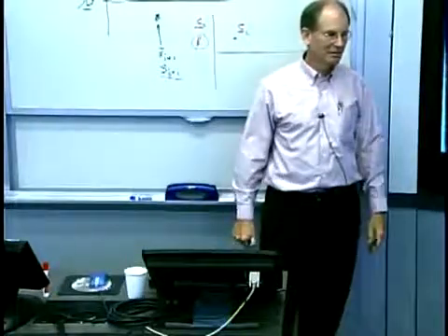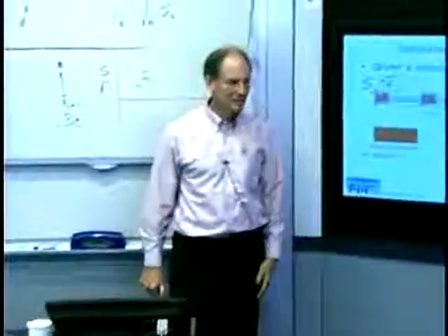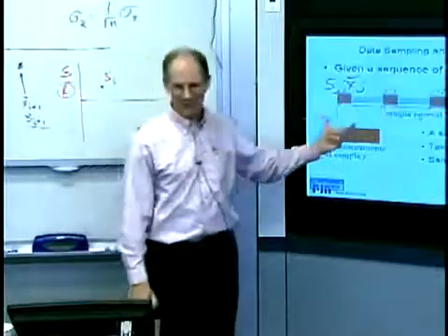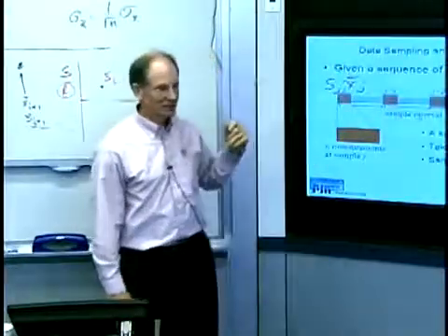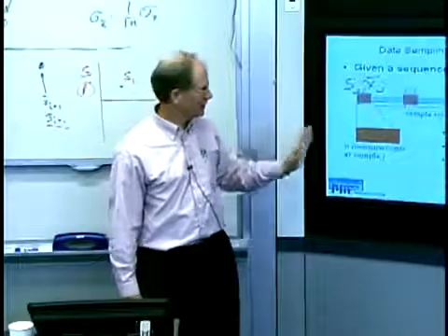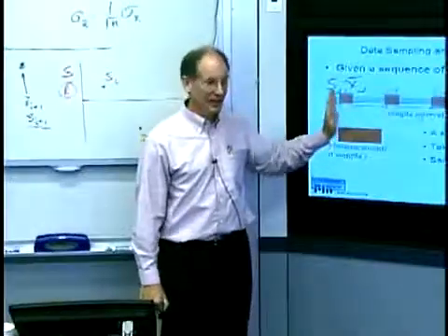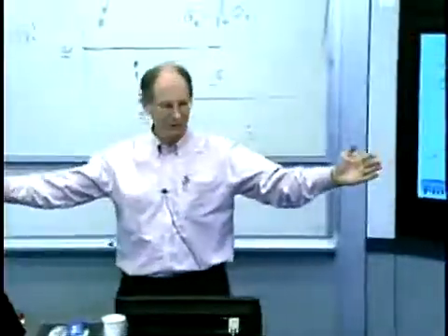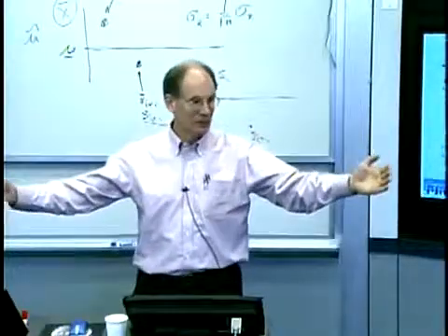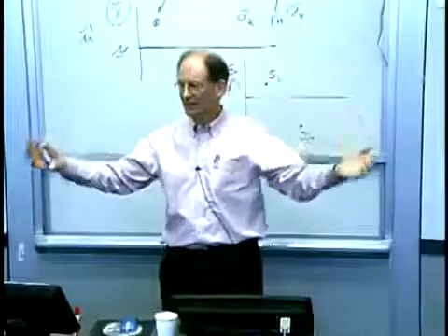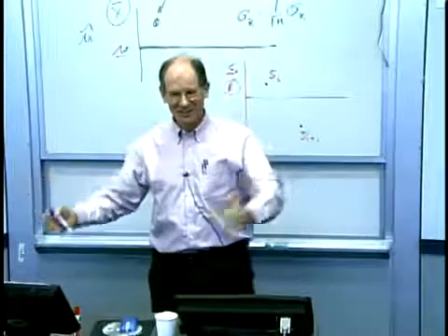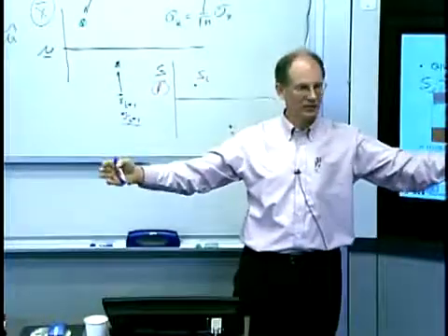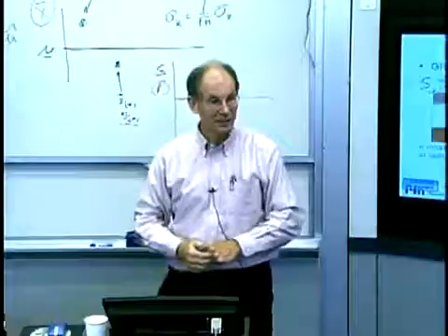Also, it would depend on your cycle time too. I mean, if your cycle time is 15 minutes, to get a sample of size 50 isn't really that hard. Yeah, it could take you all day to get a decent sample size, right? And there's a real issue here that comes up called time variability. If you took a large sample, 50, 100, a whole day's worth of production, and said, okay, that'll give me a great estimate of the mean, right? But during that time, the process could have been going all over the place, changing here and there, and you just say, well, let's wait till the day's over and see how we did. So it doesn't give you a lot of time to intervene.